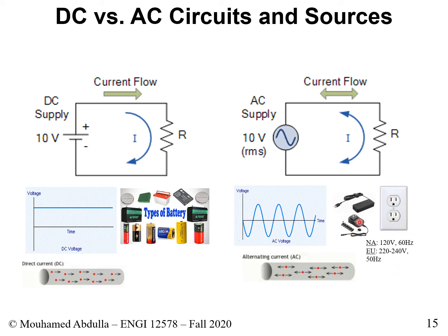Any of these different adapters that you have, what they do is take AC from the wall, and what you get on the end that is connected to the computer is DC. All electronic components operate on DC, but they are fed through AC. So you get AC, it goes through the power supply, it changes the AC to DC, and what is fed to your machine is a DC source, and that's how your equipment is charged. The same thing is with your cell phone, which you charge from the wall when it's connected to the socket.